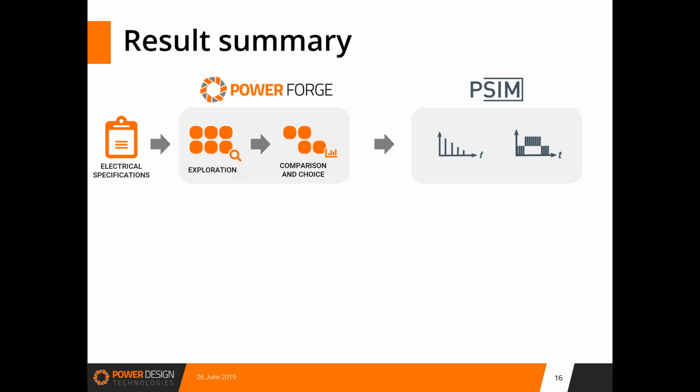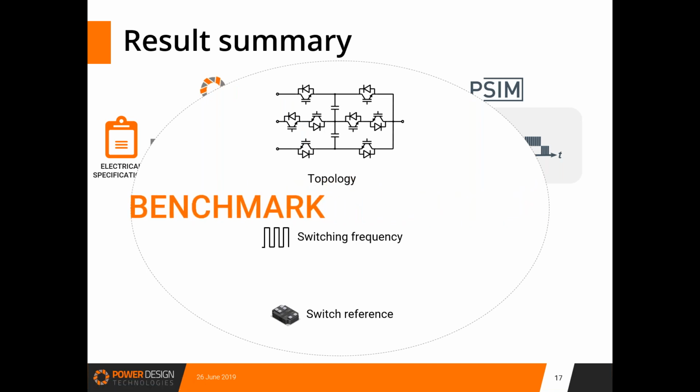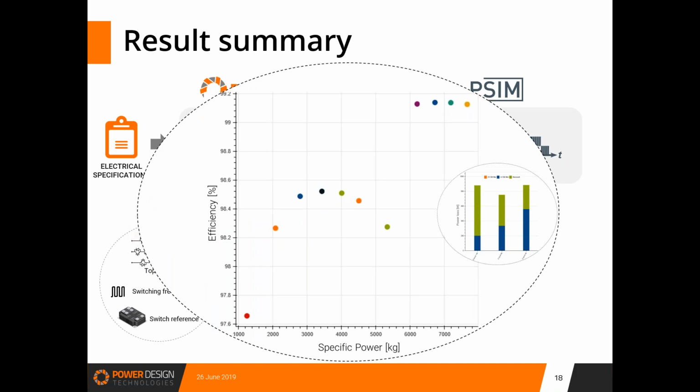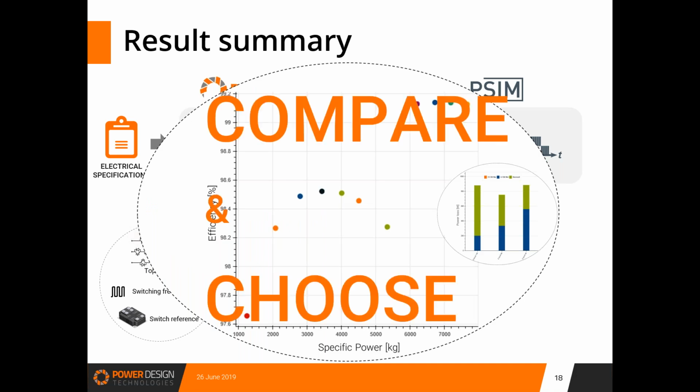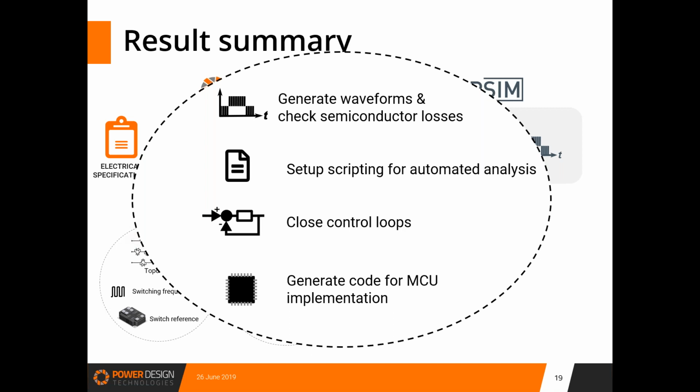First, we have shown that the user has the ability to benchmark different topologies, including multi-level topologies, but also power switch reference and switching frequencies. So using PowerForge, the user can compare different solutions and choose the ones which match his requirements, and then export this solution in PSIM. And then maybe Albert, you can summarize your thoughts.